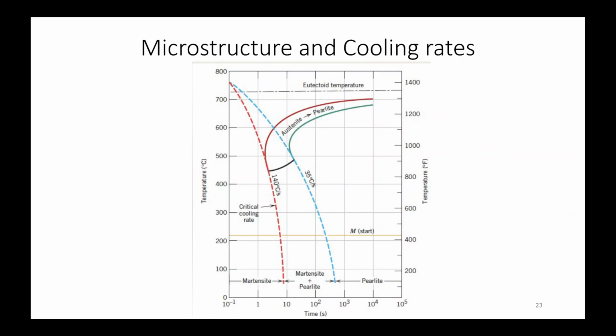Okay, so it will be constant only in case of a pure metal or where it is a eutectic type of composition. Eutectic composition has a fixed ratio, or a metallic compound is forming. That particular point will also have a constant temperature. Other than that, you are getting a phase field, right? So there will be ferrite, there will be liquid, so there will be two phases, so a slope will be there. It won't be at constant temperature.